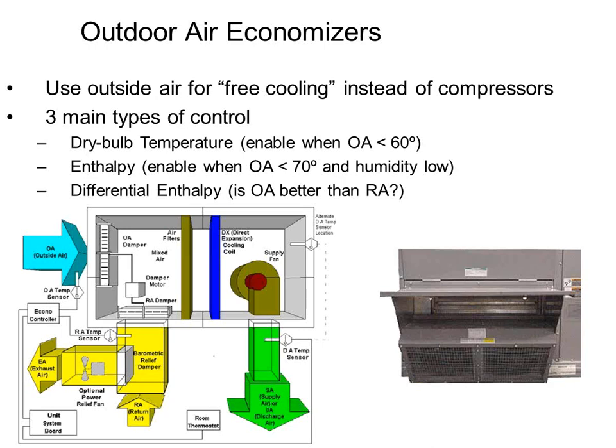Can I cool your building with 70 degree air? Probably not, but it's better than the 75 or 78 or 80 degree return air that I have to pick from. I can only get air from two places, right? The outdoor air or the return air duct. Well, if the return air duct is 75, 76, 77, 78, I'd rather have the 70 degree air. I'll have to use my compressor also, but it won't have to work as much.